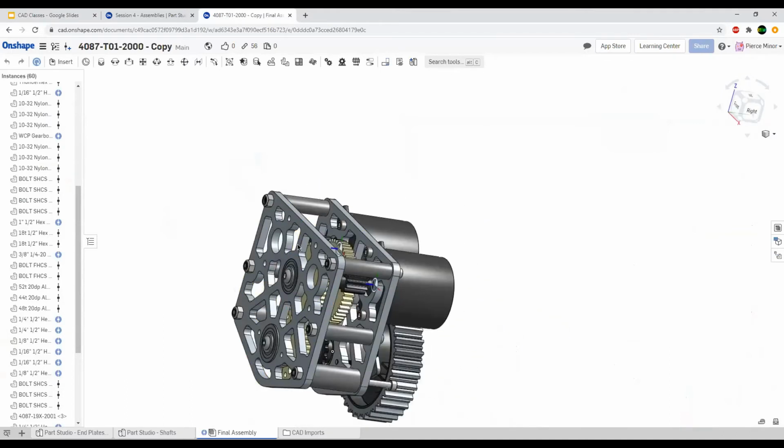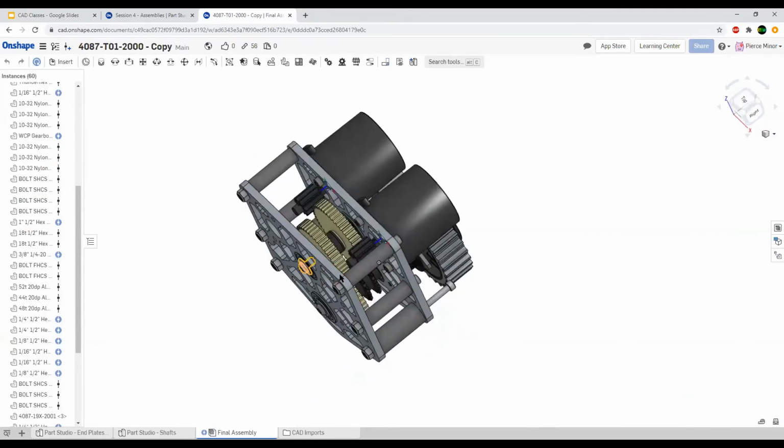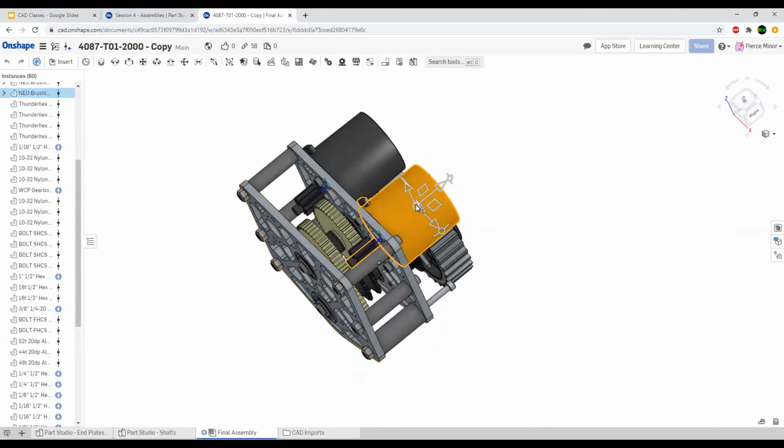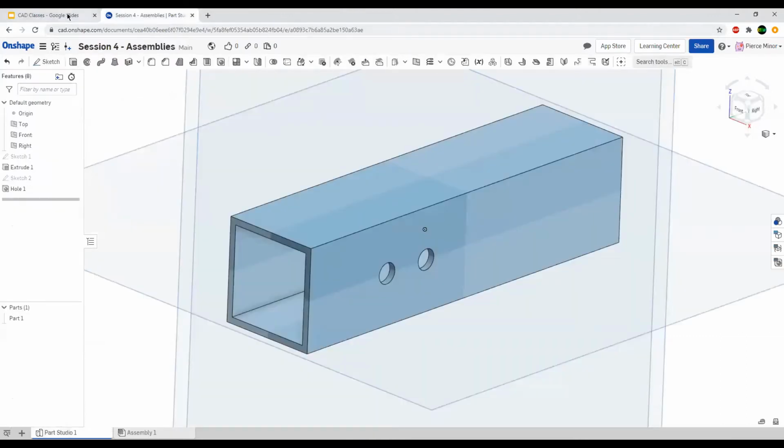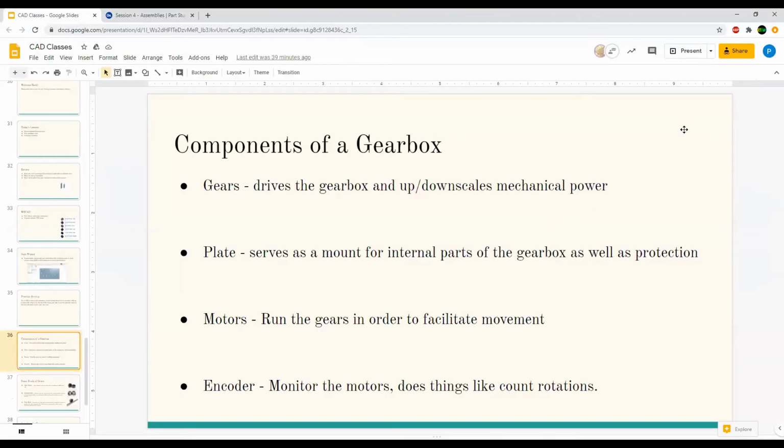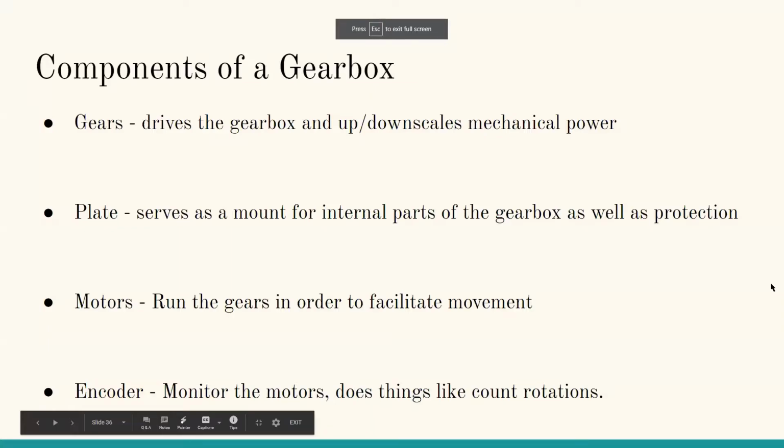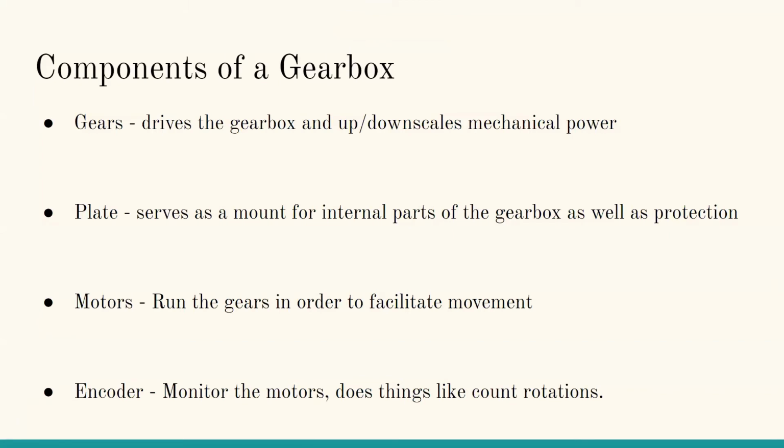Thankfully, the motors we will be using today, which is a Neo 550, I think, well, the Neos, they have encoders built in, which is super helpful, although they're not quite as accurate as a purpose-built encoder. So if you want high precision, you might want to look into actually building a mount for a proper encoder, figuring out how those work.